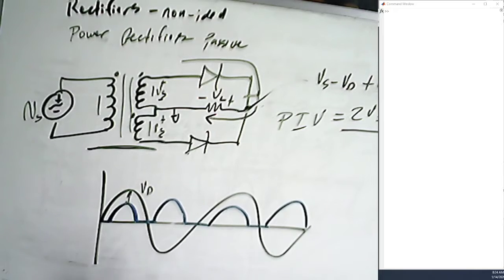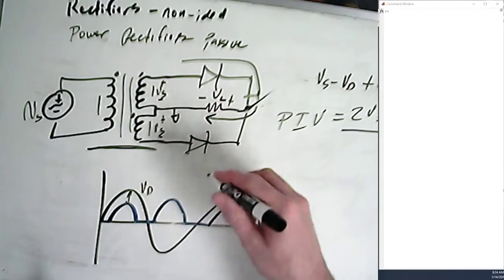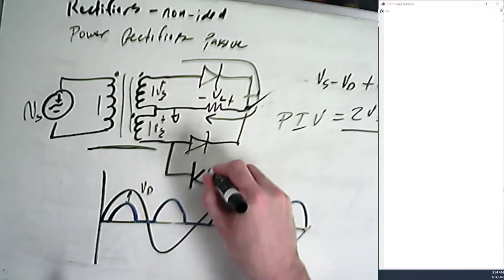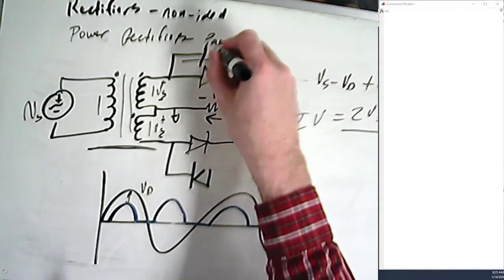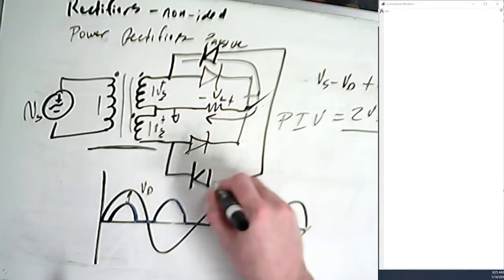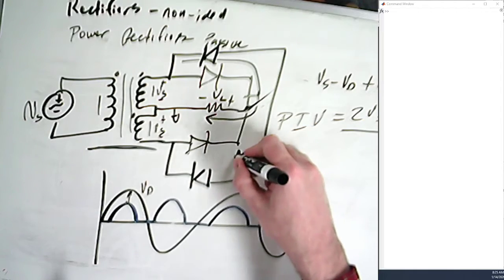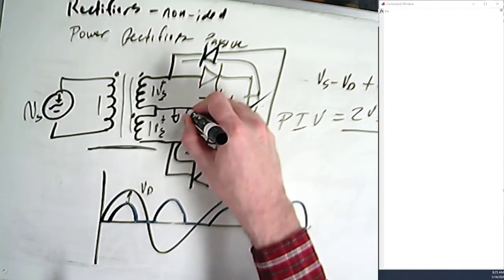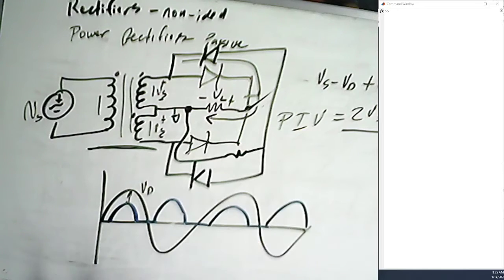And in fact, when we teach the 101 class, what ends up happening, we end up using 4 diodes, but we use these 2 diodes to give us a positive voltage. And we use another 2 diodes here to give us a negative voltage for this one. So we end up doing this to give us both positive and negative voltage. You could probably think that in a computer power supply there's both plus and minus 12 volts.